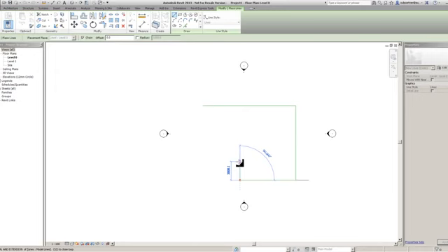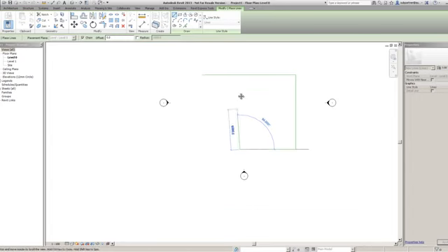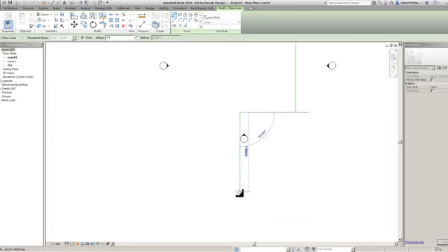Well, instead of getting my calculator out and trying to convert things, what you can do in this, if I've got to draw a line, let me just pan down here, at 15 foot. What I can do, if I just bring my mouse down in the direction I'm going to go, is write 15.